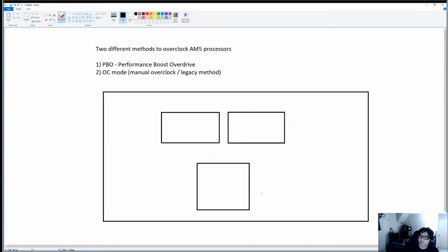So they're able to get a lot of efficiency in terms of the process node by using two different technologies. 6 nanometer is easier to manufacture, a little bit more mature, older, not as high-end, so to speak. So they're able to save costs on their I/O die. This chiplet architecture has been around since the days of Zen 2.